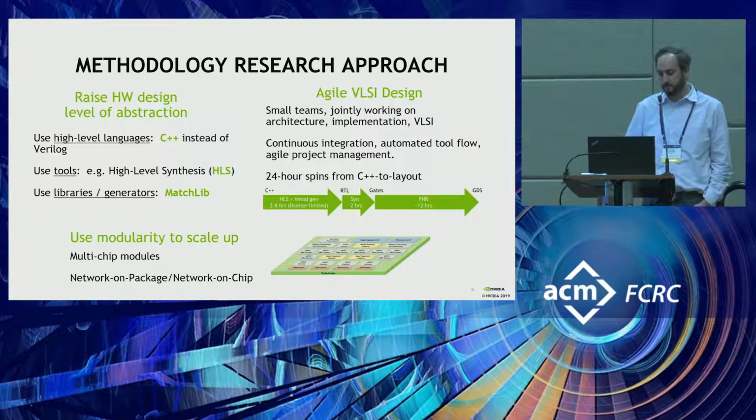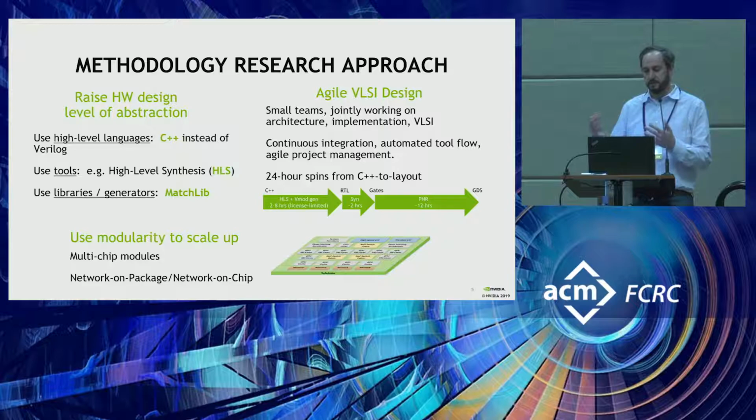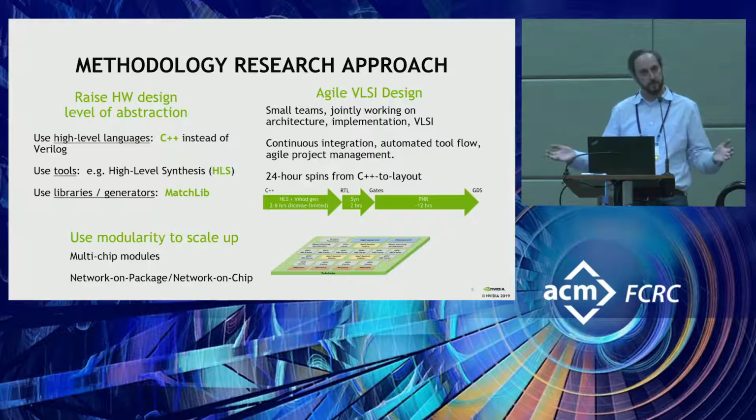We've also been working on Agile VLSI design, and the way we think about Agile is we want small teams designing chips or designing units, and they should be jointly working on architecture, implementation, VLSI together. We should have many iterations through the full flow, like maybe, let's say, daily iterations. The projects that we've been doing are about 6 months long, so maybe halfway through the project, we just want to start doing daily iterations all the way from C++ to layout.